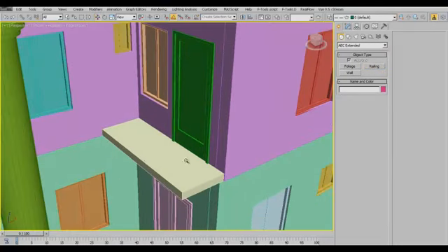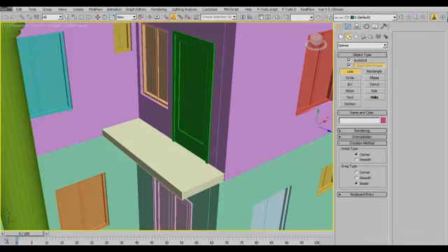So what I'm going to do is draw a spline across this area to create our railing path. I could just do line and turn on my auto grid, bring this guy, holding my shift to constrain to a particular axis, and equally still holding my shift to constrain to a particular axis. If we don't hold shift, it goes in various directions, so I hold my shift to constrain to a particular axis.